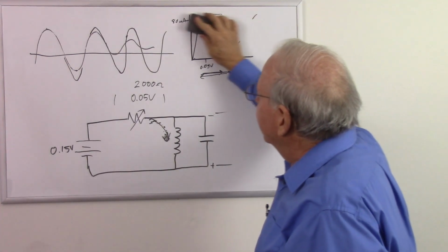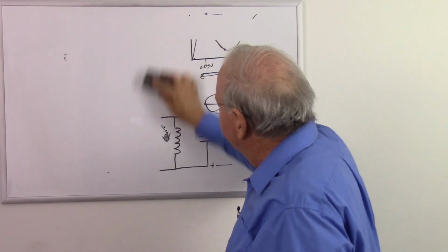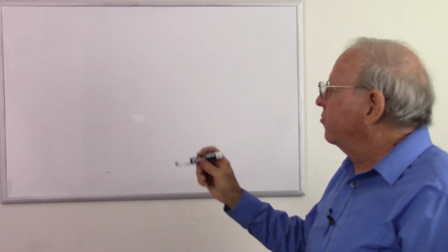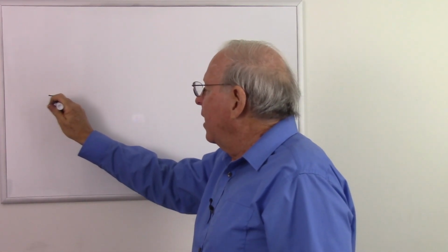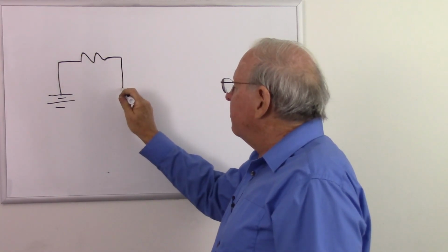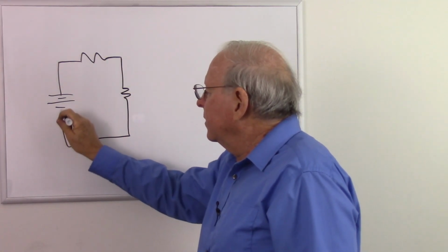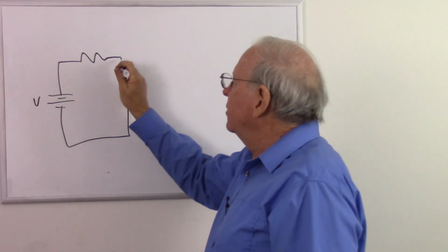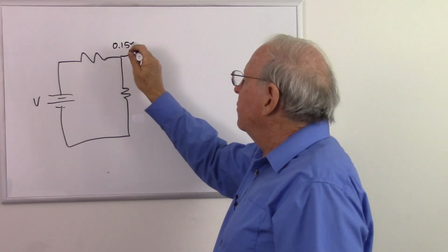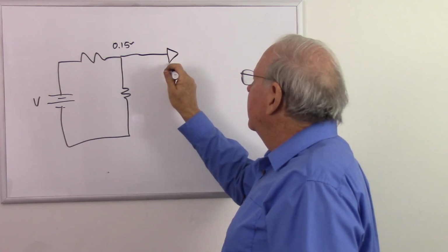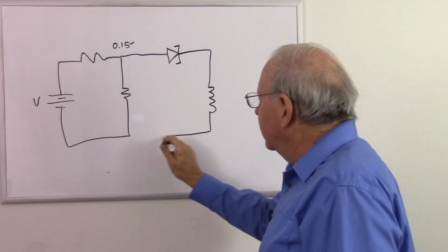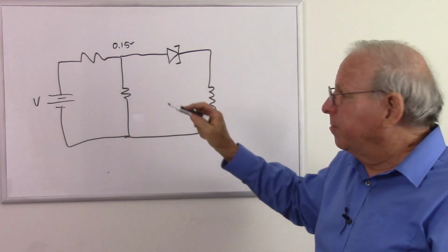So now that we have done that, let's just draw the basic circuits just to put them up here, and I'll put the ones that we can do in the simulator up also. So now here is your typical relaxation oscillator. We go through a couple of bias resistors. So this is going to be some voltage, but we use a voltage drop to put this at about 0.15 volts. That goes to our tunnel diode and then to an inductor. And it does what we explained before.